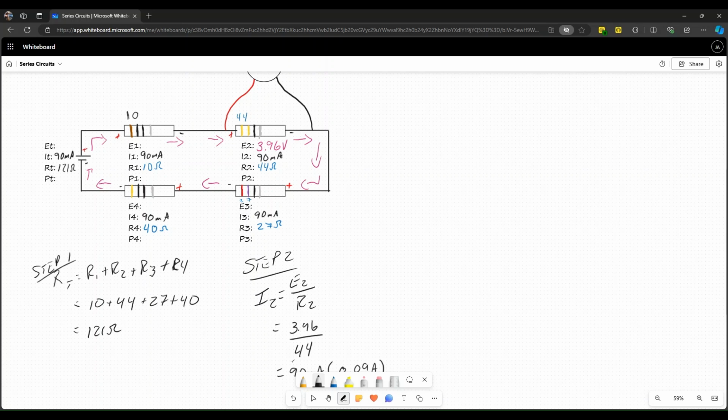So once I solve the one, the rest I just fill in. Because again, IT equals I1 equals I2 equals I3 equals I4. And we knew I3, therefore they equal that one, that one, that one, and that one. They're all the same. So now we have two values at every point. It doesn't matter what you knock off. Now at this point, it is just Ohm's Law. So you know what? Let's just finish off P2. Let's just do that one.